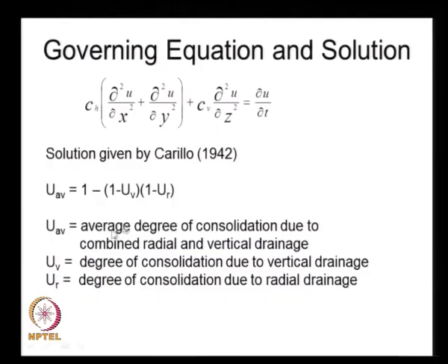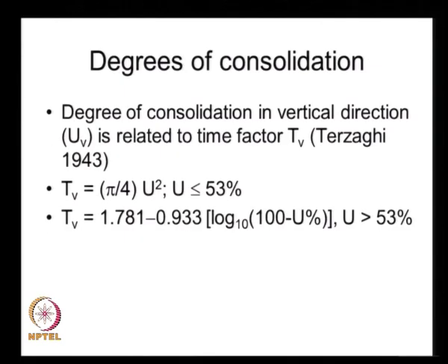And the principle for designing is, in a certain time, we would like to achieve, let us say, 90% of the consolidation, and so we need to design the spacing so that the net sum total of the consolidation that we can achieve because of the combined consolidation is so much. And the solution for the